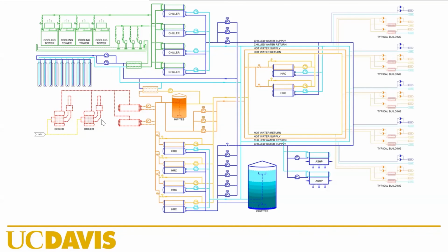And so the ultimate goal, shown here, is a geo exchange system where, when we can't get enough heat out of the buildings in the winter, we can run that chilled water into the ground, get it back up to 60 degrees, and that's enough to run it through our heat recovery chillers and make hot water in the winter. It also shows potential air source heat pumps. You could do the same thing to heat that chilled water back up in the winter when we need more heat to run our heat recovery chillers. So we'll either have one or the other or a combination of both for a fully electrified, carbon neutral heating system.